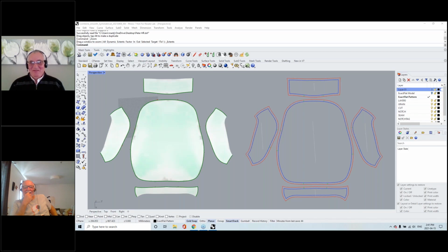Thank you. I have a question for Peter. With the Peel scanner, are there any object size limitations? They're not absolute limitations. As you scan larger and larger objects, you have an effect called the volumetric error effect that comes in, and that is the length of the scan path. So if you were to, for instance, scan a yacht and you started from the rear and went clockwise around that yacht, you'd have a good chance of having a scan path of 20 meters at least. Now, the volumetric error is, I believe, 0.25 millimeters per meter of path.